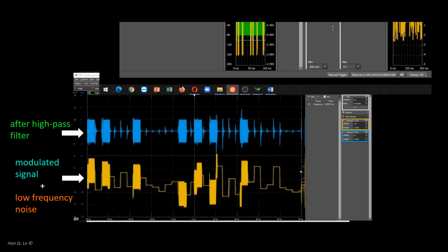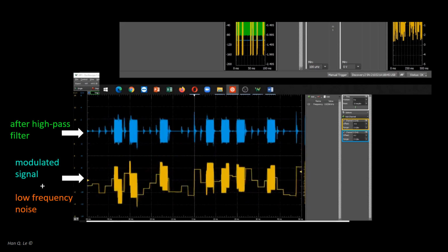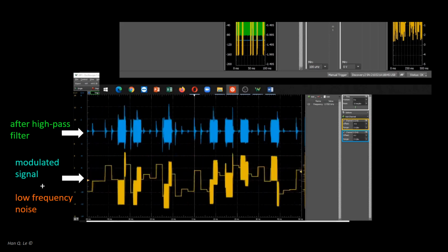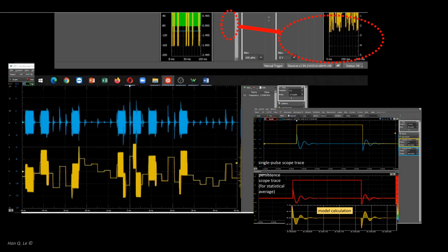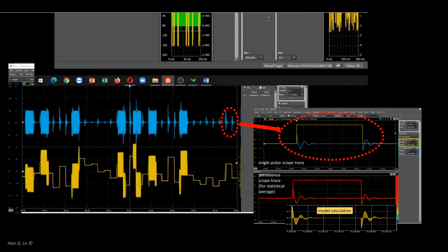The main effects of the noise with abrupt level changes are the spiky oscillatory step responses that were studied in Lab 6 Part A Step 3. This spiky behavior is inevitable and harmless, as it will eventually be filtered out by the demodulator circuit later. However, if a more conventional filter is desired, there will be an option for a flatter band top, as discussed in Lab 6 Part C.